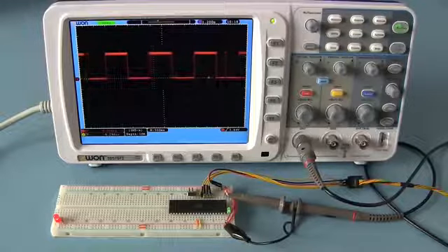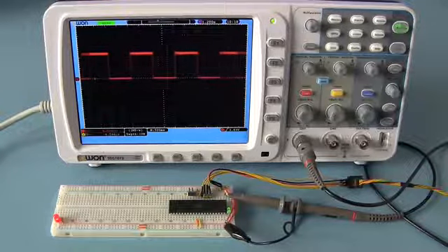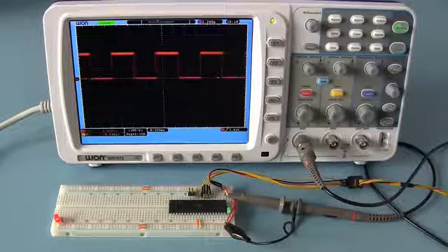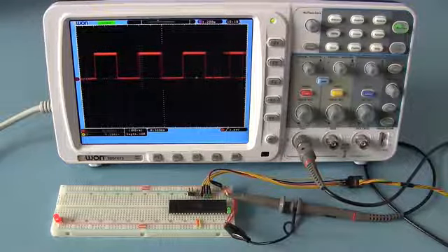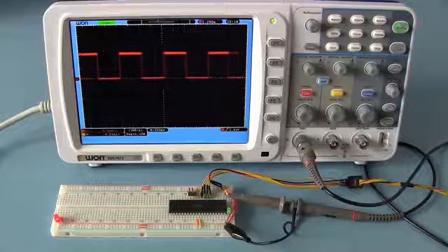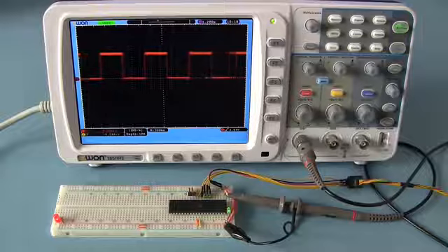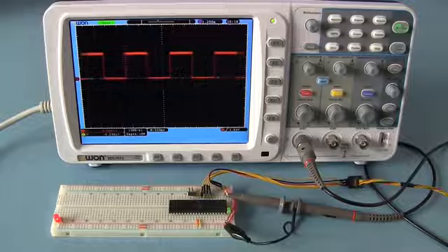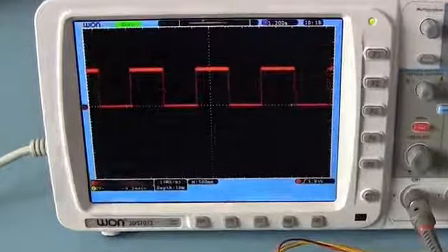In this video I will be using an oscilloscope to show the results of some experiments. To better understand the results, I will first explain the workings of an oscilloscope. An oscilloscope visualizes the voltage at a certain time. It will plot the voltage points along the horizontal axis, and the vertical axis represents the measured voltage at that specific moment in time. So when I connect the input of the oscilloscope to a blinking LED, we can see the voltage rise and fall over time.